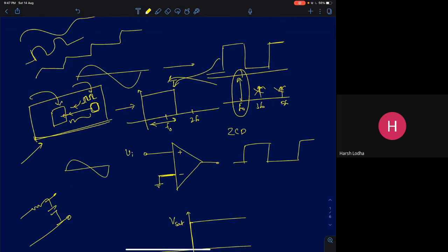Now, I've discussed extensively how to find the Fourier transform of a square wave signal, and you can go through that. A 50% duty cycle square wave signal will contain only odd harmonics of the fundamental frequency. A pure sine wave will just contain one tone at the fundamental frequency f0, whereas a square wave with fundamental frequency f0 will contain a range of harmonics from the fundamental all the way till infinity. If I pass this through a low pass filter, all the higher harmonics are going to get rejected.